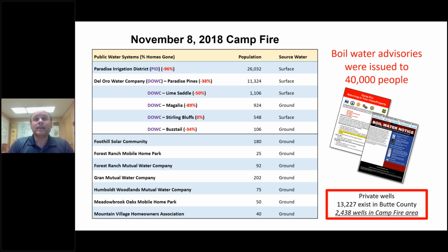So we got involved in the Tubbs fire because after 3 or 4 months of flushing contaminated water, and they were unable to reduce the contaminant levels below safe limits, somebody told the city of Santa Rosa to give me a call. My prior experience was working with the military on decontamination of infrastructure after accidents and terrorist events. So when you have bad stuff in your system, how do you get it out? And what's the best way to do it? And so once they told us what levels of contamination they had, we basically said, well, you need to start removing and replacing infrastructure. You cannot flush this away. It's too significant. And so they started doing that.